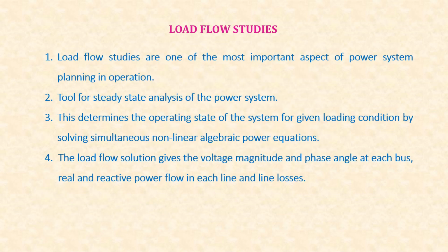The load flow studies give a steady state solution of the power system network. The problem consists of determining the magnitude and phase angle of voltages at each bus and the active and reactive power flow in each of the transmission lines, together with the power at the reference bus.